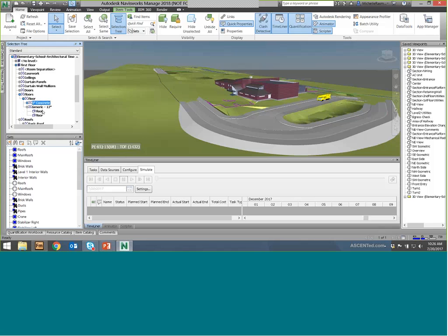You can lay the concrete, then you can come back and do the other floors that are on that first floor. And so if I wanted to just lay that concrete right now, I can come in and do a save set, and in the save set, I would tell it exactly what it is. Because when I use those rules to automatically connect my tasks from the timeline to the objects in the model, it's going to look right here in the save sets for that. The next thing you might want is to actually pick like your windows,